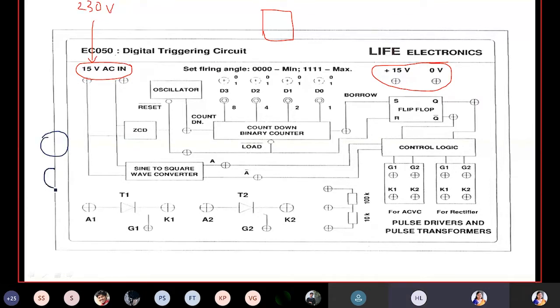Excuse me, ma'am. Ma'am, in SR, the 1 1 state should not be allowed, no, ma'am. JK toggles. Yeah, it toggles. So whenever the 1 state appears here, that is a flip flop. That's not a flip flop, that's a latch. In the SR latch, it will toggle. In the SR flip flop, the output will be changed from 0 to 1.